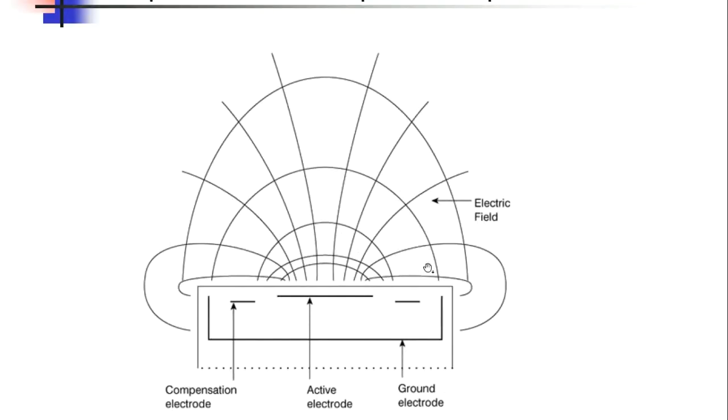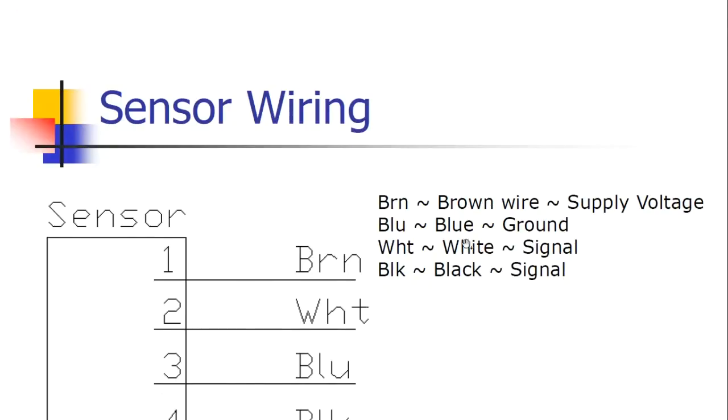So basically they use air as the insulator between the two plates. But if a piece of plastic or a human hand or a bottle of water comes down and enters into this field, then that affects the voltage on these plates. And so that sensor can then detect that, hey, that object has changed my voltage, so I know something is there. And that's how those work.